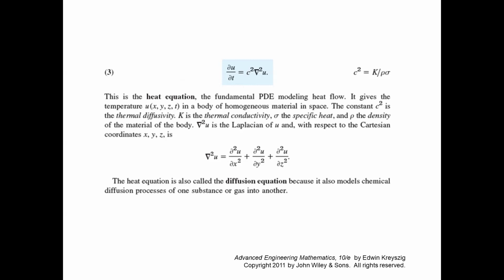Also, let me make another comment. This operator called Laplacian, if we have a heat transfer in a spherical object, if we immerse a copper ball into a hot oil bath, then the temperature rise inside the object can also be analyzed based on this equation, but the operator can be represented in spherical coordinates.